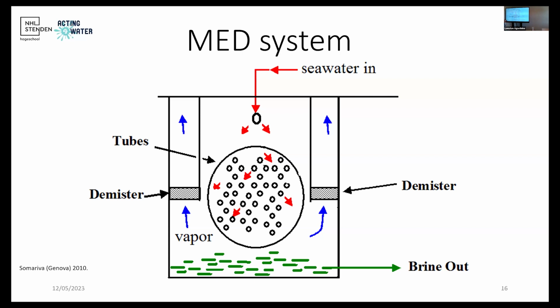So what you have is that your seawater will be put into your system in a shower. The top showers or the atomizers will generate the necessary surface area so you can evaporate. Then the shower will be heating a tube bundle process where you have your hot vapor passing inside. As soon as you shower, the internal water vapor inside will condense, and you get your condensation as pure water.